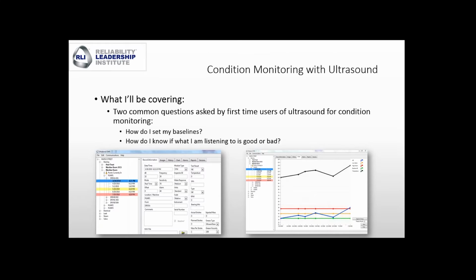And that's really making use of recording the sound of what we're hearing, whether it's onboard sound recording. With some ultrasonic instruments, we have the ability to actually view that in real time as we're out collecting data. But we can record the sound of what we're hearing, and we can then play that back in spectrum analysis software to where we get a visual FFT and a time waveform. It paints a picture as to what it is that you're hearing. So we can then diagnose inner race, outer race, cage faults, or ball pass frequencies. We can see well-defined harmonics, and we can then diagnose problems.